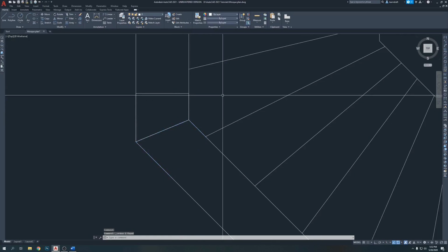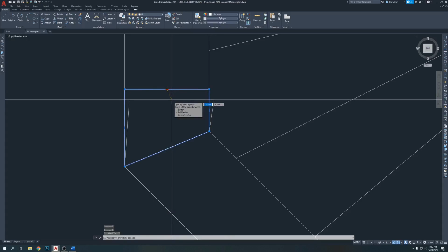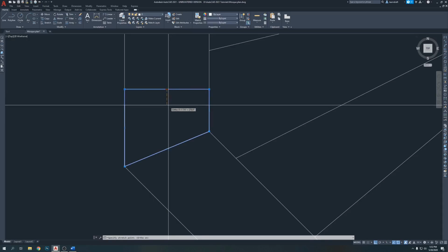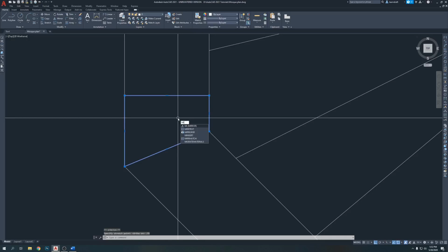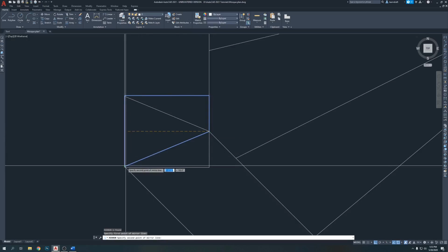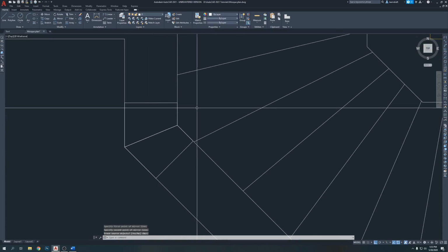But what I'm going to do, I'm just going to bring this one like, okay, F8 is off, so bring it like, if we bring 1 inch, the inside is going to be 7. So let's make it actually 0.75, like 3/4 inch. Mirror, press F8, enter, click here. Actually you can click there properly and enter, it's going to be there.